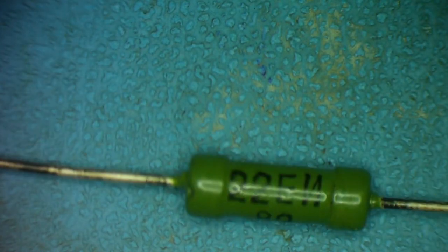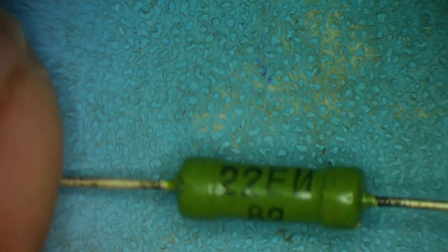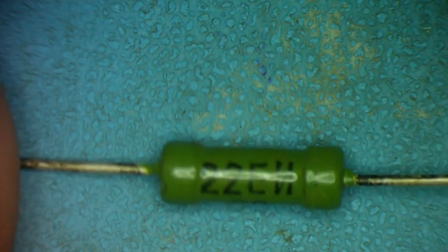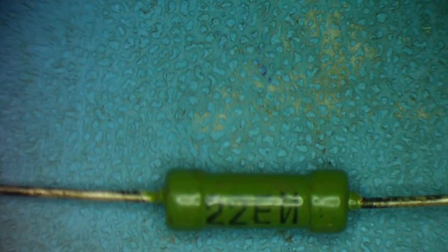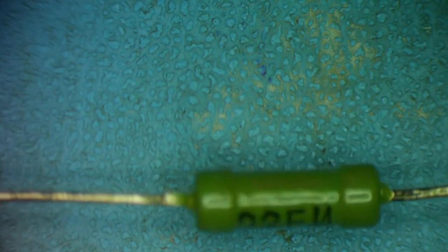This one is a little wirewound resistor. This is marked 22E. It's Russian. That's an I. That funny backwards front end is actually an I. That'll be 22. I know it's a 22 ohm resistor. I mean, if you're not sure, you can just get your meter on resistance mode. Just measure it, you know. But that's a 22 ohm, and I know these are little wirewound type resistors.